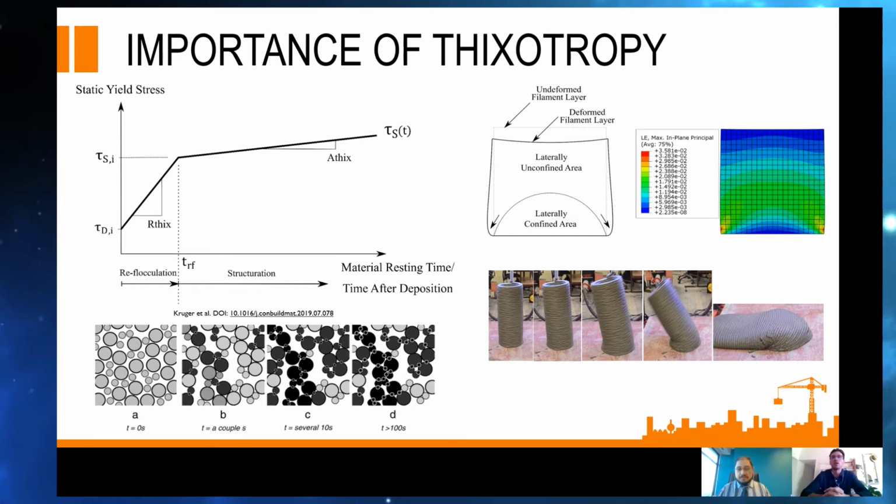So for 3D concrete printing, what this means to the general public is there's a certain time frame in which you can 3D concrete print, within which you can deposit and actually use this material to print. You can't after a day reverse this process. You can until its initial setting time.